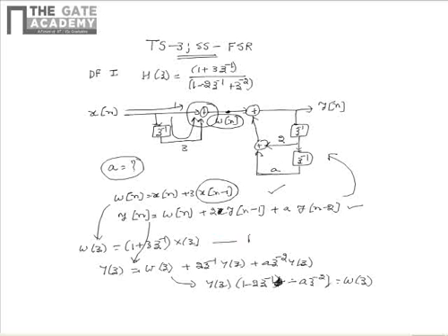So upon using the two equations that we got in Z transform domain, that is 1 and 2, we see that Y of z divided by X of z can be written as (1 plus 3z inverse) divided by (1 minus 2z inverse minus a z power minus 2). This is actually the Z transform of output divided by Z transform of input, hence this is the system function.